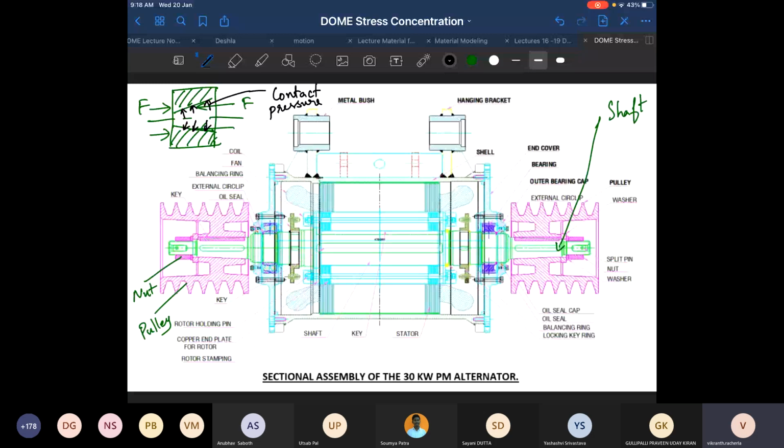See, all of you have taken part in first year and second year workshop, right? Now, in a CNC machining center, when they have to change the tool, the tool spindle has got this tapered surface, nice polished tapered surface. They insert it into the matching taper, and then they tighten it a little bit. That's it, and that will be able to transfer the torque. So anyhow, you have this tapered surface.